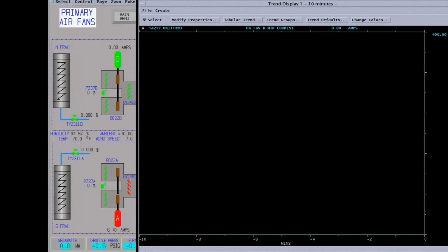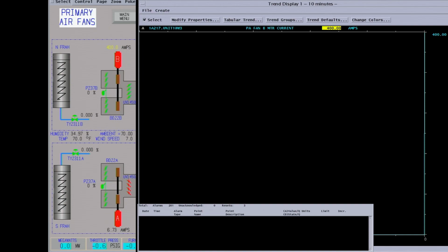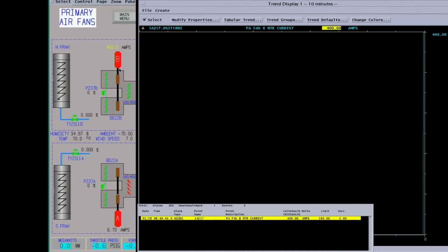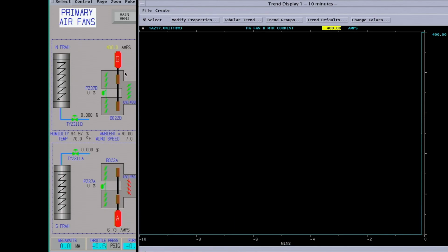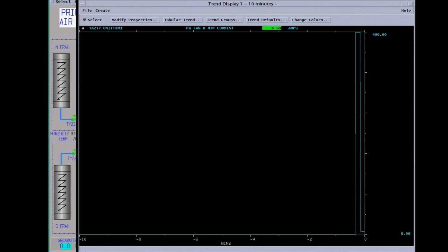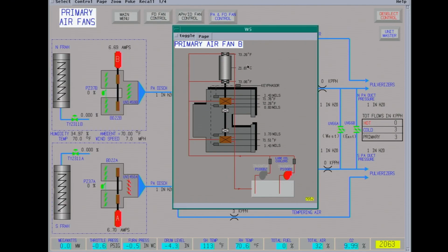Okay, you're starting the primary air fan. There's a lot of heat in these motor windings when you start them. Once these are running and we have the pressure set, then we can go ahead and start the pulverizer. Quick check, motor temperatures are good, bearings.